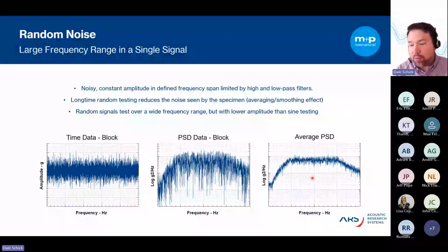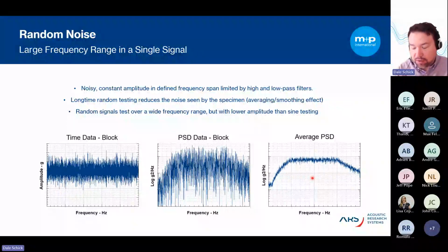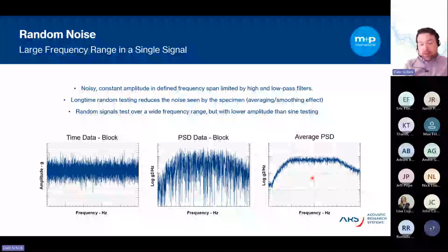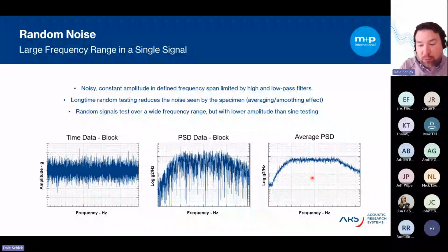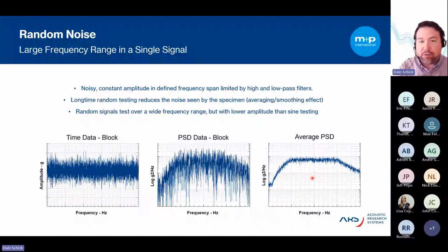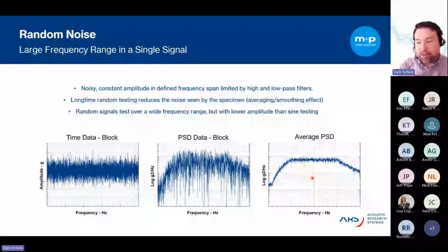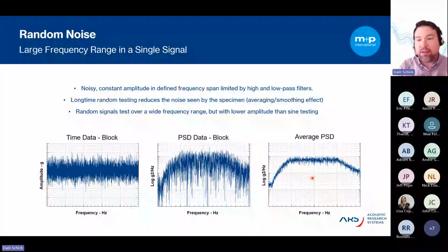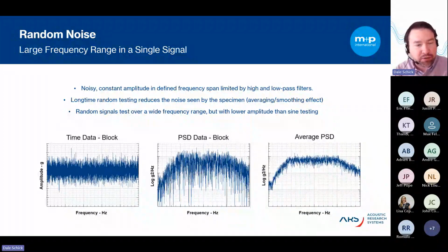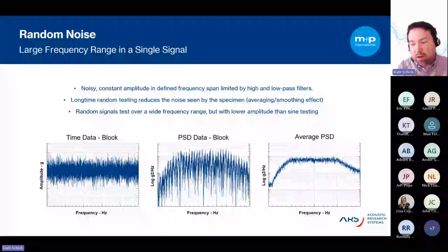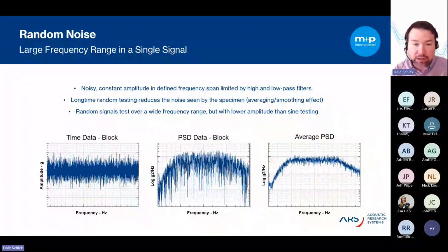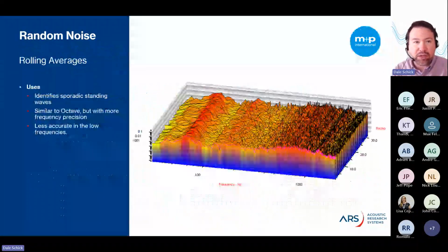So it's really important when you're processing acoustic data, both acceleration and octave data and narrowband data in the spectral domain, that you use linear averaging to properly characterize all of that data from the full exposure of the test. So if you're running for 60 seconds, for instance, every second of that 60 seconds is averaged linearly together. So you get a true mean of the data.